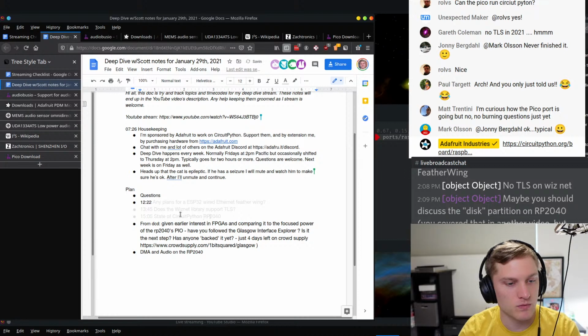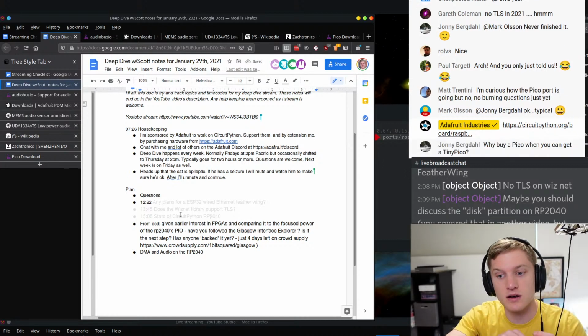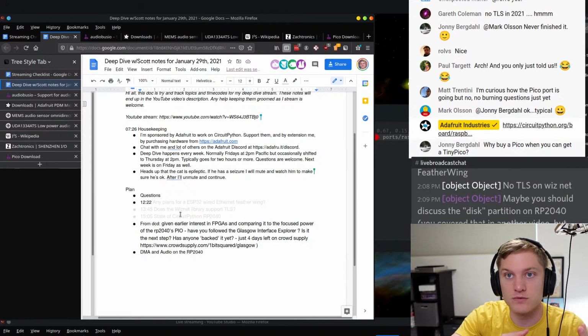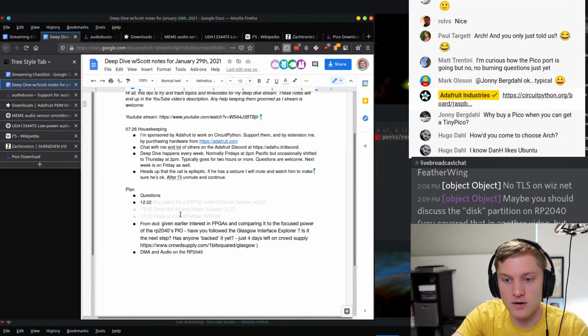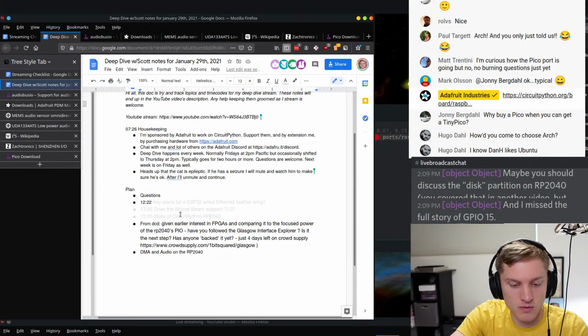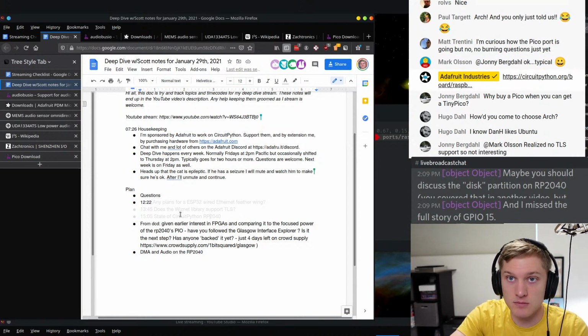So I would say we're a lot of the way through. We have kind of what I would consider the core of CircuitPython. So all the USB stuff works. They use TinyUSB in the Pico SDK, so that just works, which is great. So that means we have mass storage, CDC, HID, MIDI, and that works. We have busio, but in busio we only have I2C and SPI implemented. I haven't done UART yet. A couple people have done that.